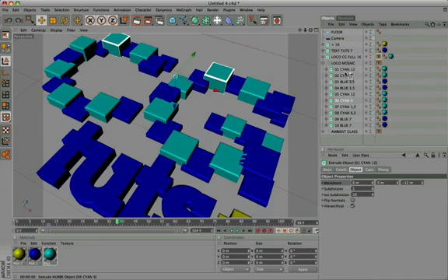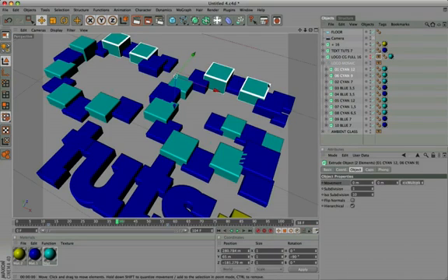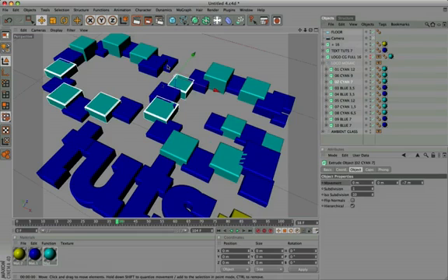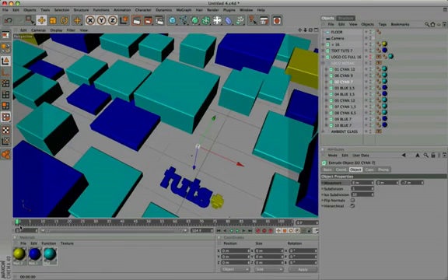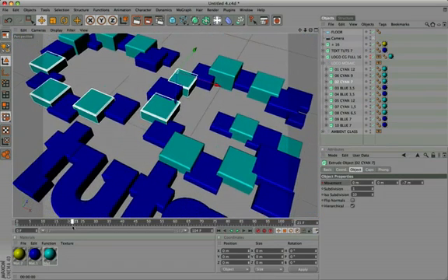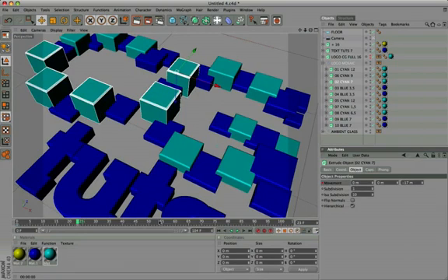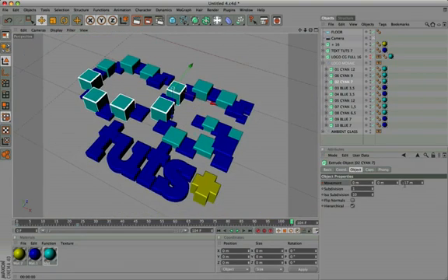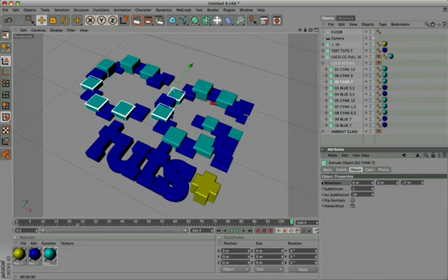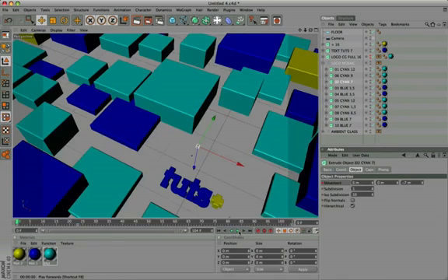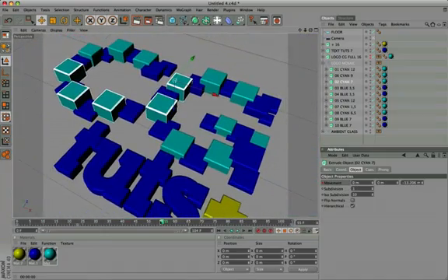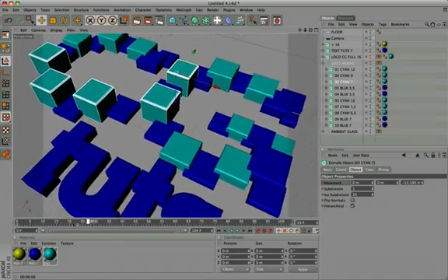The layers 01 Cyan 12 and 06 Cyan 9 are without animation. Select the 02 Cyan 7 layer. Go to frame 0 and apply the first keyframe on movement, with the default value 7. Let's move the timeline to frame 23, change the value from 7 to 17, and activate the keyframe. Let's move the timeline to frame 104 and restore the value 7, and activate the keyframe. We see the animation. We applied the animation with vertical extrusion movement.